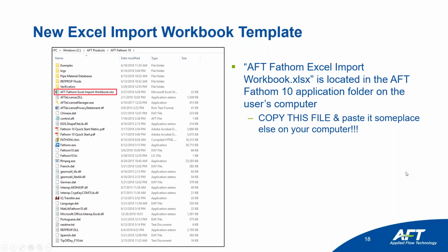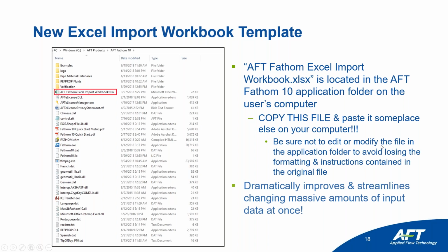Here's my advice. Copy this file, paste it somewhere else on your computer, okay? The reason why is because this is the file that comes with the software. You do not want to change this file and muck it up. So copy it and paste it somewhere else, and then work on that file that's saved elsewhere on your computer. That way you can preserve the full functionality of that file. This dramatically improves the importing capabilities.